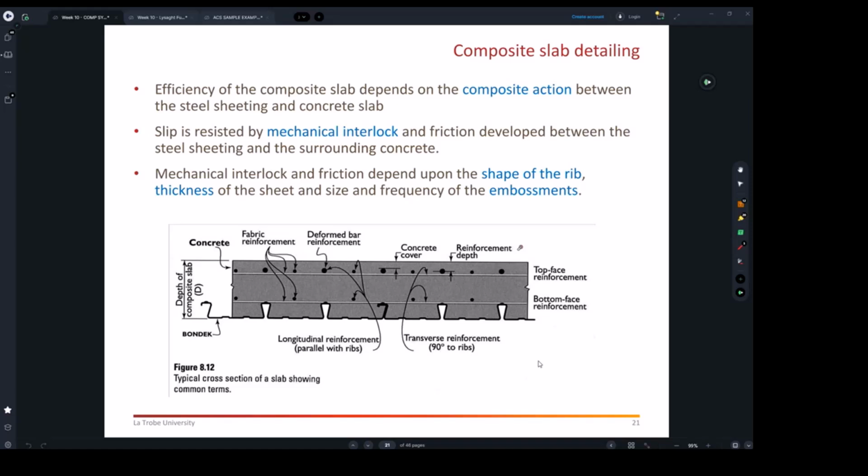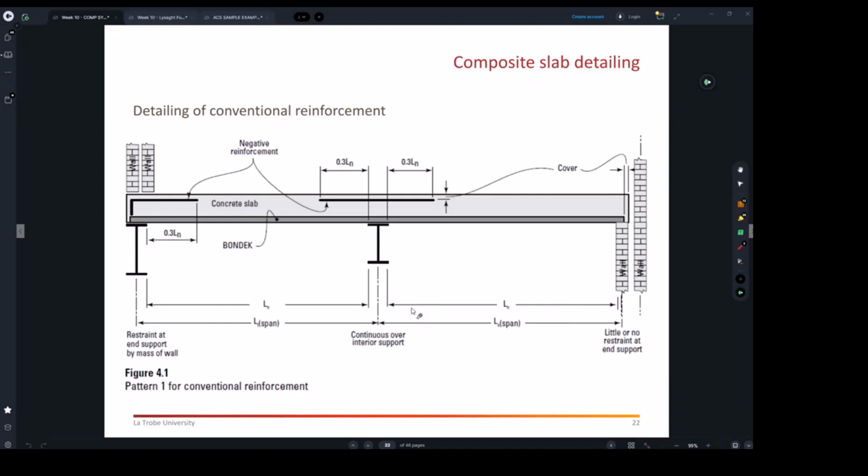There are decisions made on different sites where the builder may choose a different profile, but they didn't know there was a reason to use that particular type, because it was used in the calculations. So you just need to know that changing the profile of the product is not just a different brand name. It can be different in the capacity we need to resist.